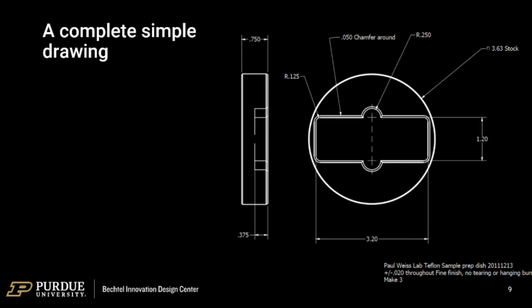This is another thing about a drawing: it should have only the dimensions it needs. It shouldn't be over-dimensioned and it shouldn't be under-dimensioned. You should be able to completely manufacture it by referencing each number one time, so to speak.